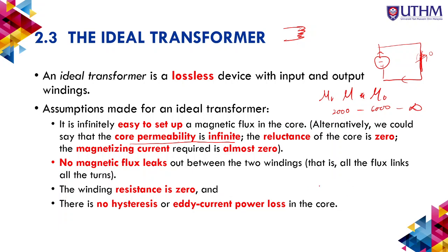Once the flux flows through the core, it will induce a voltage, and the voltage will also induce a current. If we cut the core from this side and look here, the flux goes through like this. Using the right hand rule, the eddy current will be produced circularly like this.